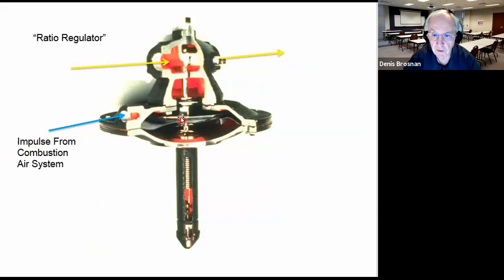And we've got a diaphragm here, a stem that's poking upward with a disc on it to open by raising upward, or to close partially or wholly going downward. In this particular case, there's a diaphragm, but there is a pulse of pressure coming in from the air system. Okay, and it's the pressure that moves this diaphragm right here, up or down.